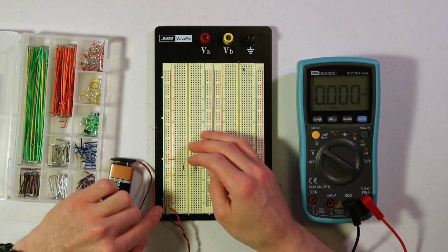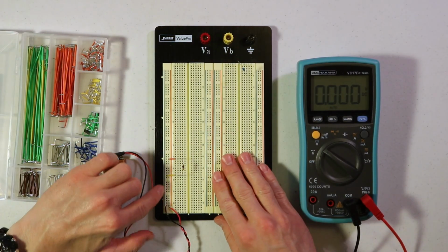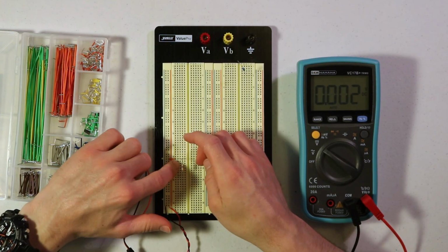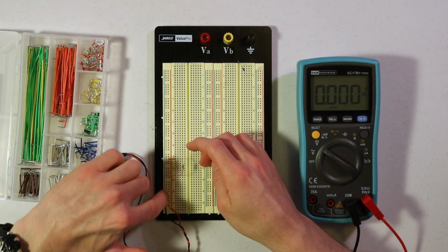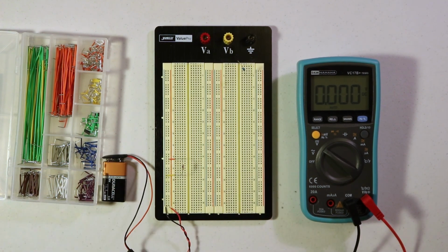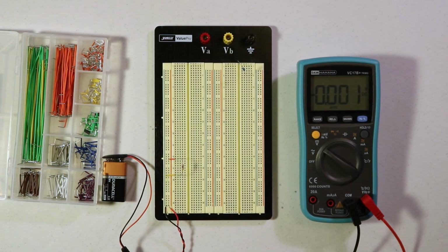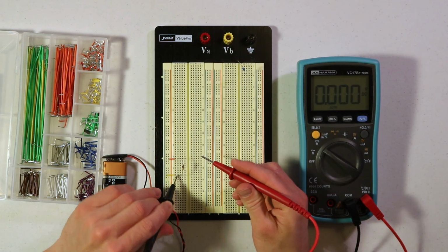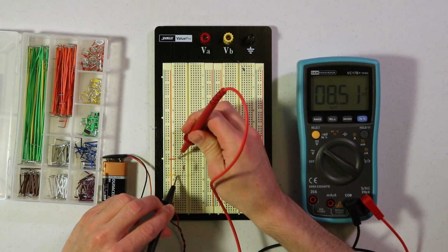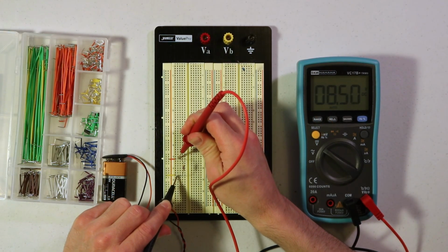Alright, so now I've got the negative line on my battery going in here, coming over to this part of the resistor, and then the positive line here. So positive through the resistor to negative back to the battery. And we can check now, we've got it on voltage. So if you just place your probes across the resistor, the same way we used to measure the resistance, and just place it right like that, and see what the value is.